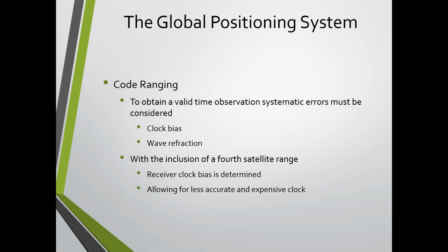So, a good example is a temperature correction with a steel tape. That's a good example of a systematic error. We recognize that tapes will increase or decrease distance with increasing or decreasing temperatures. So by measuring the change in temperature and using the coefficient of linear expansion for whatever material you're using, you can predict the amount of error that's associated with that measurement, and you also know which way it's propagating, positive or negative.